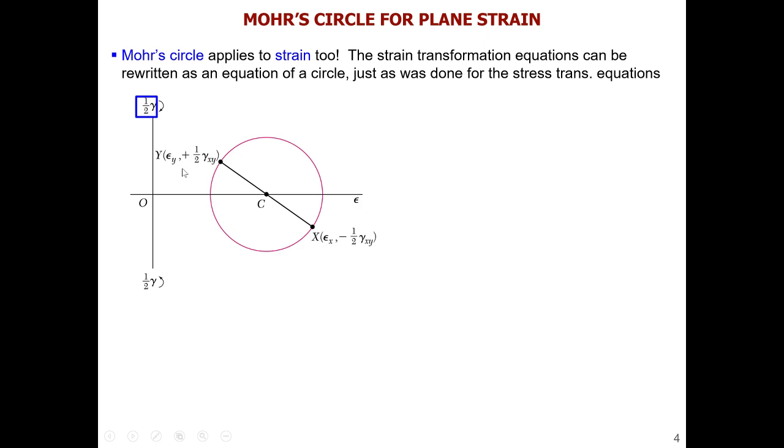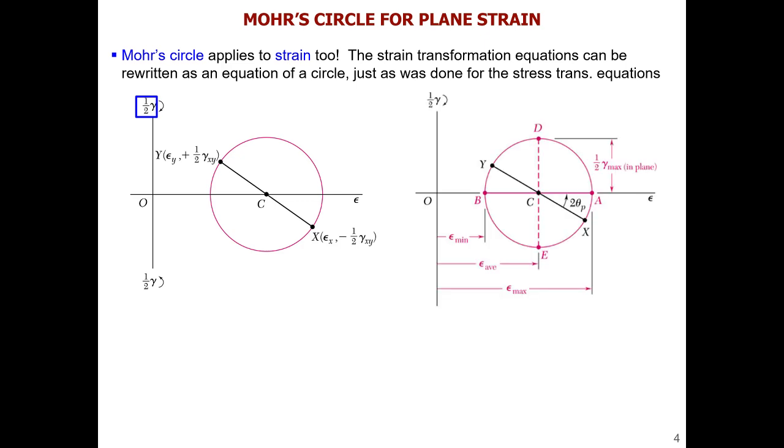And now we can use this Mohr circle to actually transform and see how the strains change as we go to a rotated system, right? Or we can find our usual important situations when we have a maximum or minimum value of the deformations that we apply, right? So there is an angle that makes us rotate to the state which is called the principal state. And when we have principal stresses and principal strains, so when we find the maximum values in that rotation for the original state, we obtain a situation when we don't have any shearing. Remember that we didn't have any shearing stresses in this case, and we also obviously don't have any shearing strains in this case. So this will be minimum, this will be maximum values of strain here.